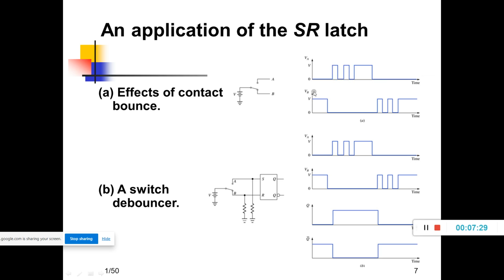Again, when going from A to B, it is going from A to B now, again 1 0 1 0, here again 0, next 1. It will then settle. This is known as contact bounce. You can see these 0 to 1, 1 to 0 transitions. Because of the springiness action of this center contact, it will switch from 0 to 1, 1 to 0, again 0 to 1, again 1 to 0.